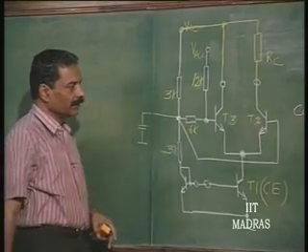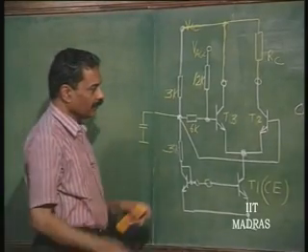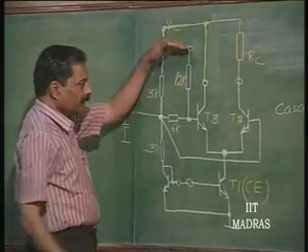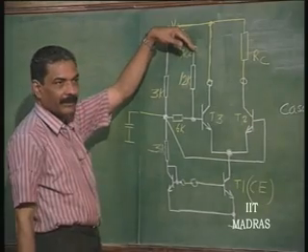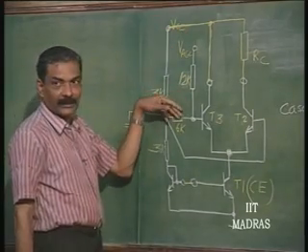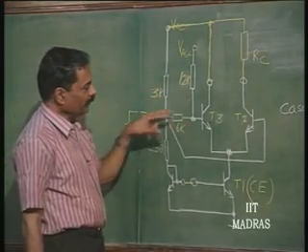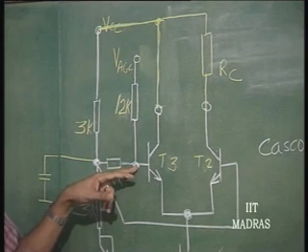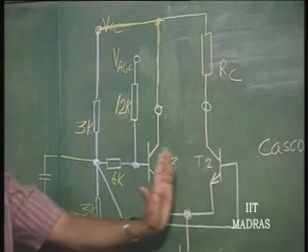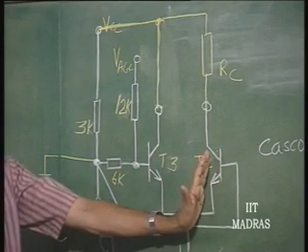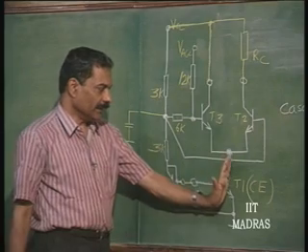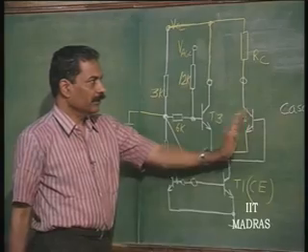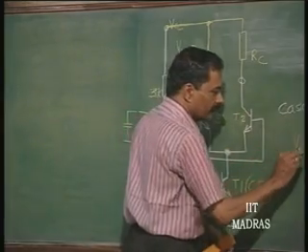This is connected to VCC, and we see that if the AGC terminal is left free, there is almost no current through 6K, and the base of this T2 is at the same potential as the base of T3, and therefore, these two currents will be very nearly one and the same. So, the current in this is going to be halved if VAGC is 0.